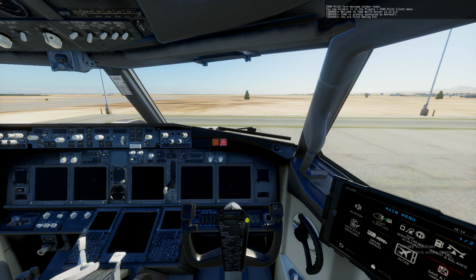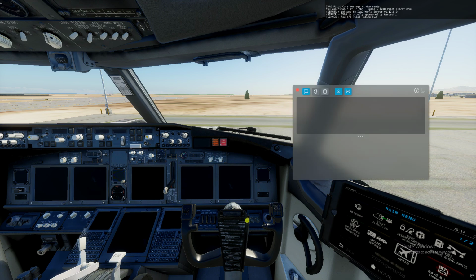So now I will read back the clearance to the ATC. Always pilots have to read back the clearances. Clear to destination Beirut International Airport via Emily 1 Whiskey. Climb to flight level 150 and squawk 6703, Prt1.